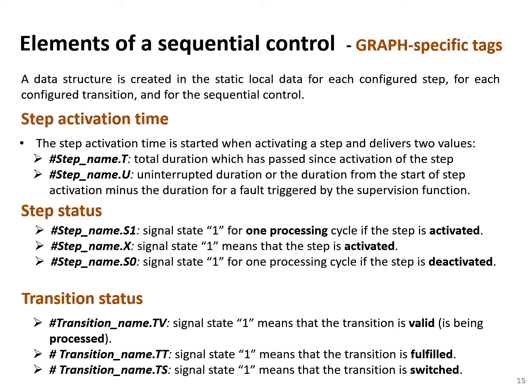Okay, so now let's see what the GRAPH-specific tags are for the steps and for the transitions. These are GRAPH-specific tags that will be created automatically by the program. Once you create the step or the transition, those tags will be included. So, step activation time.